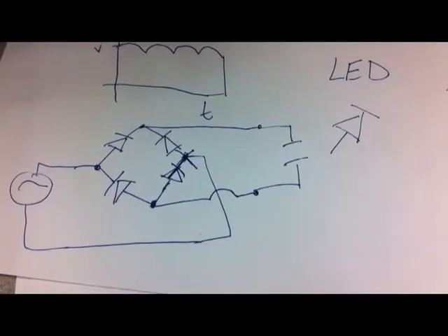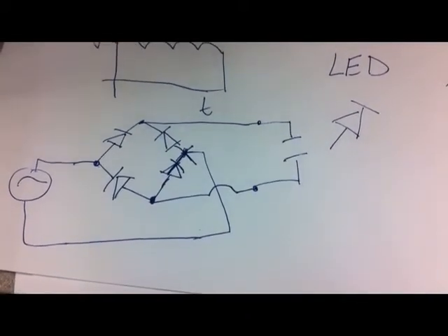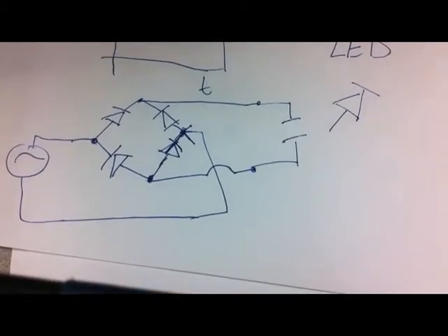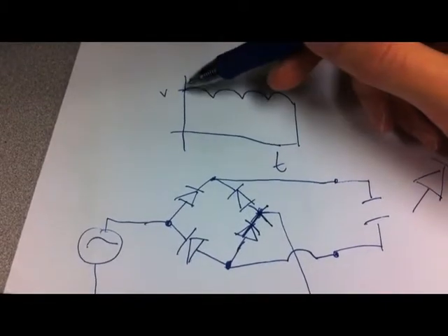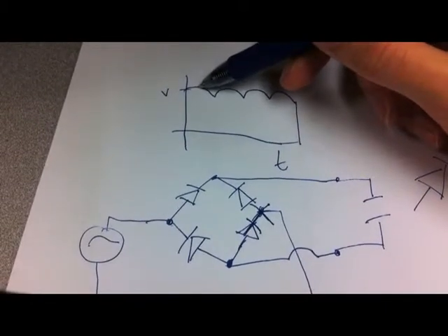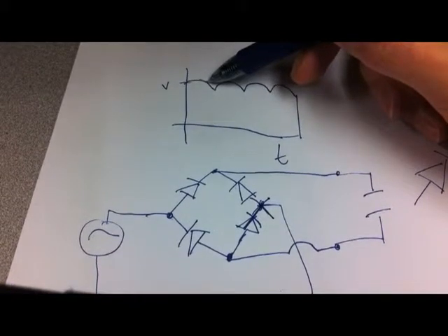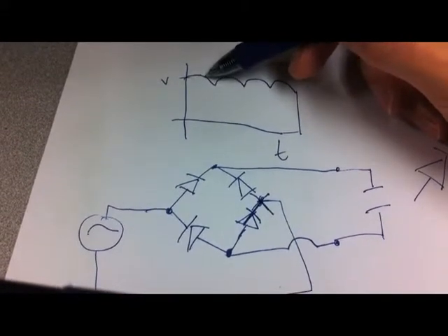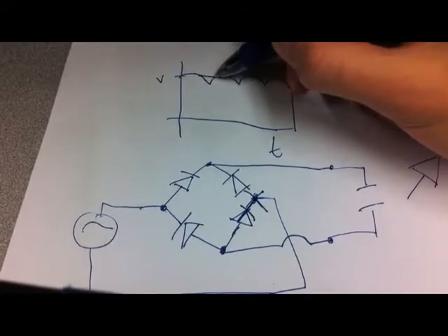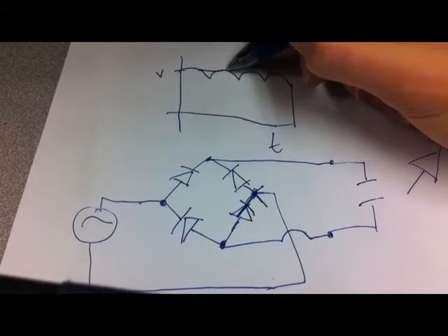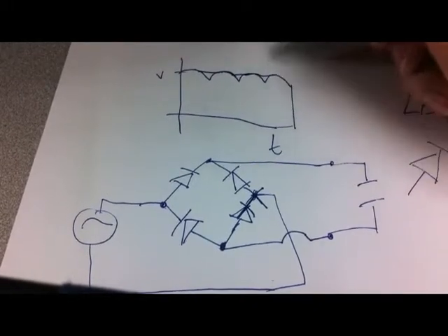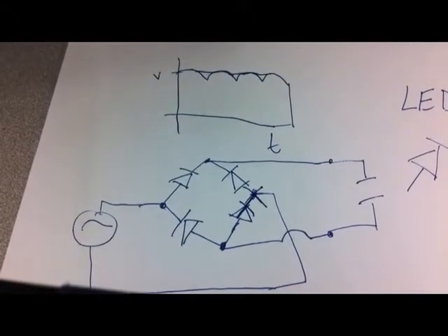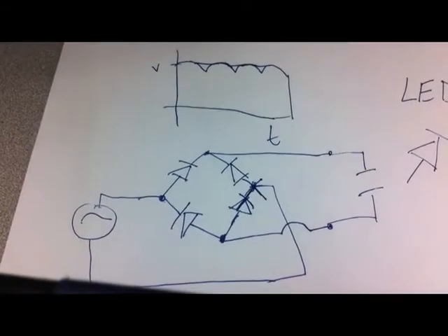What a capacitor does is it charges up and then discharges, and charges up again and discharges when needed. So when these ripples occur, at this high peak, the capacitor is fully charged. Now when this starts to dip, the capacitor is going to discharge and draw a line here, then recharge up here, discharge here, recharge here, discharge here. So there might be a little bit of a ripple still, but it's not going to be as pronounced as it is here.